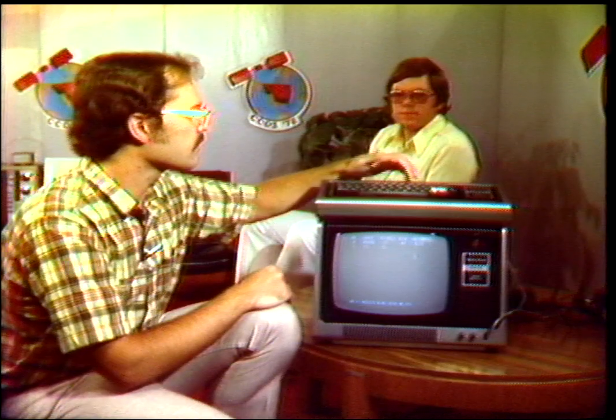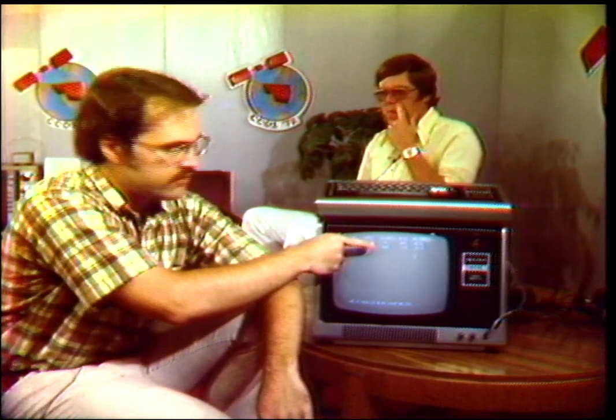So what's good numbers here, Bill? Oh, about 0.5 amps. Okay. And, I don't know, 1,500 feet. Okay, we've entered at the first amplifier 0.5 amps, 1,500 feet, and the voltage drop, it tells us there, is 1.125, and the amplifier voltage is 28.875.